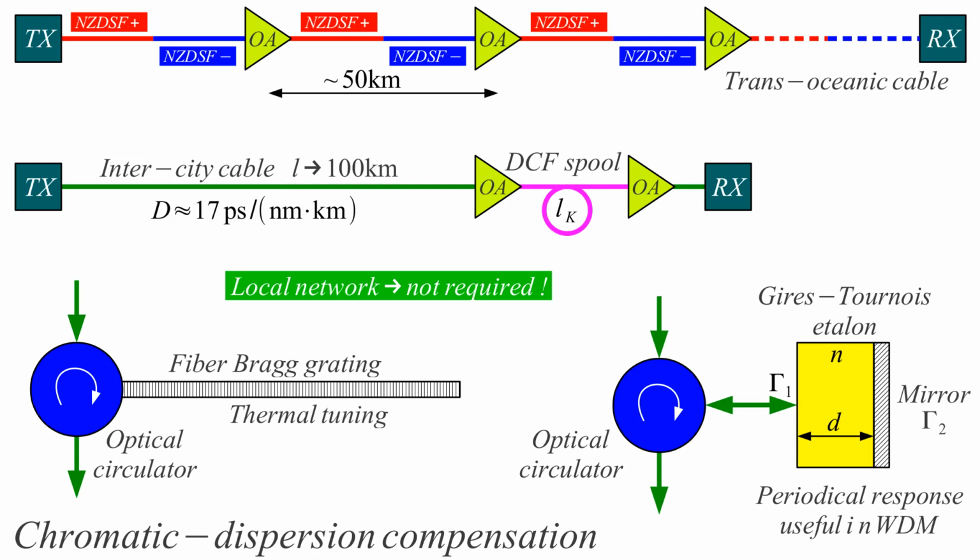So we have multi-level communication, multi-phase communication, so QAM communication, and QAM using both polarizations. We also do polarization multiplexing to get at least 10 times the symbol rate as the actual capacity of this fiber. 10 bits per second per hertz we obtain on a transoceanic cable.